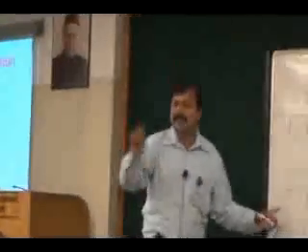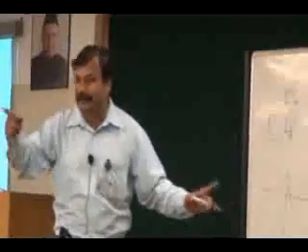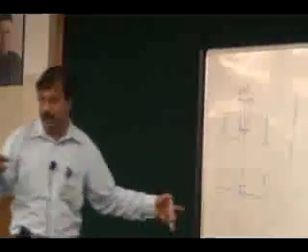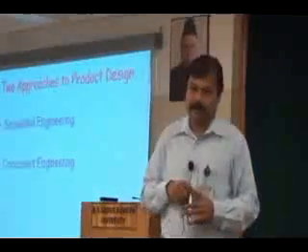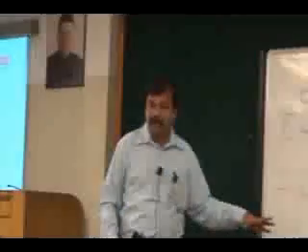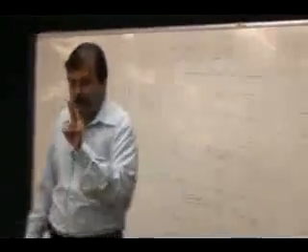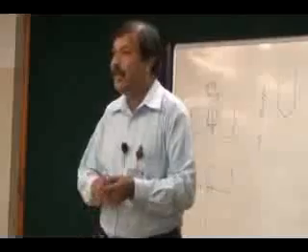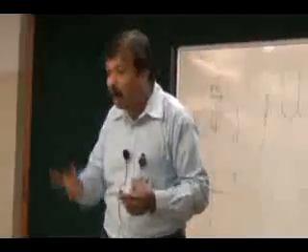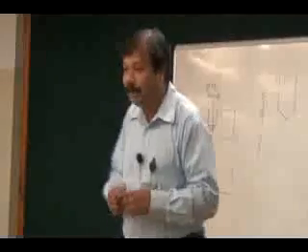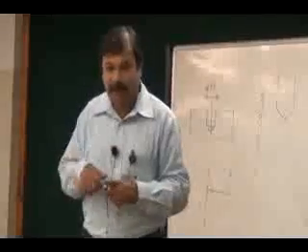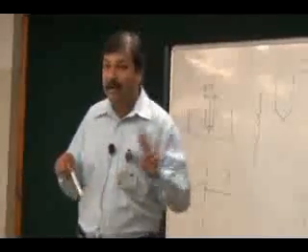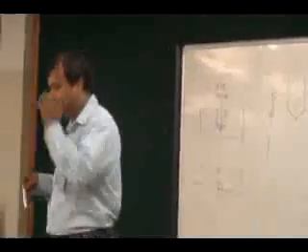I am just giving you a simple example, because only this you can appreciate. There are many such issues that only a manufacturing engineer can put forward. In the case of sequential operation, if this drawing goes to manufacturing, there are two things possible. Either the manufacturing engineer can refer it back, or he will spend 20 times more and try to make a blind hole with a flat bottom. Neither of them is desirable.